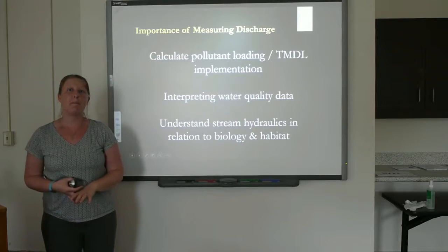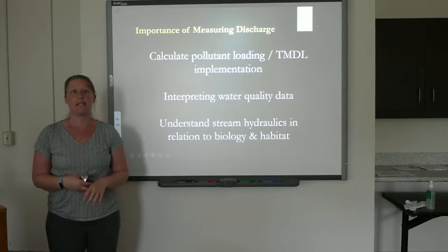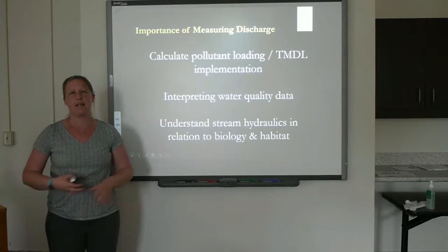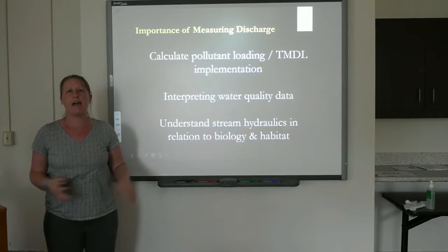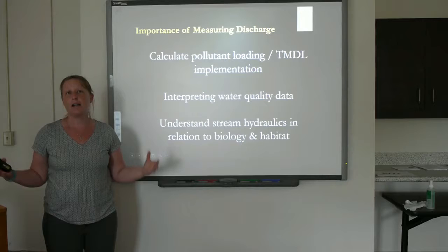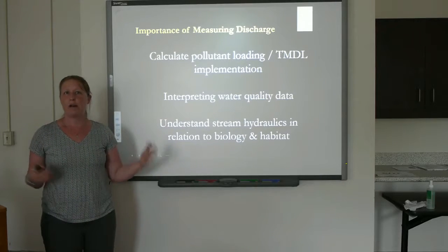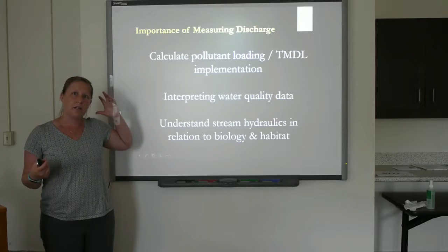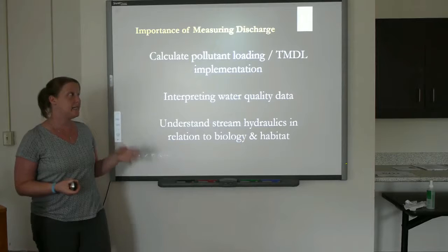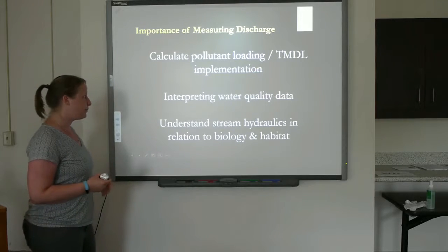Usually when we analyze for a pollutant, we analyze for the concentrations, in something like milligrams per liter. But what that doesn't tell us is the mass that we get every day, for example. So, how many kilograms or how many tons or how many pounds of acid or of metal or whatever it happens to be, do we load into this water body every day? And that ends up being important when we look at implementation of some of these regulations.